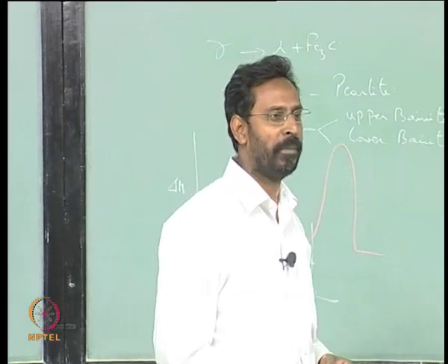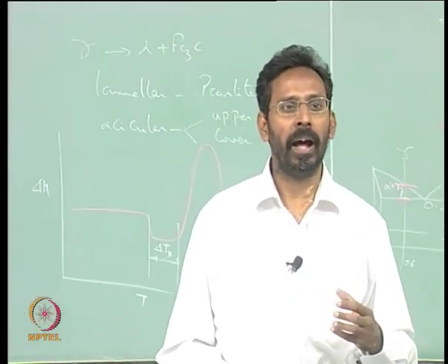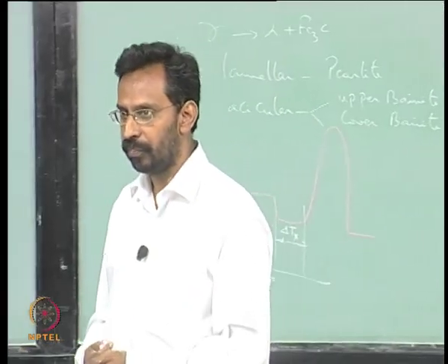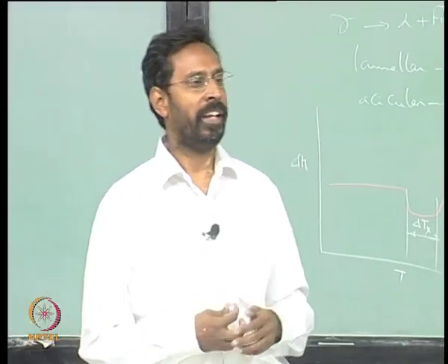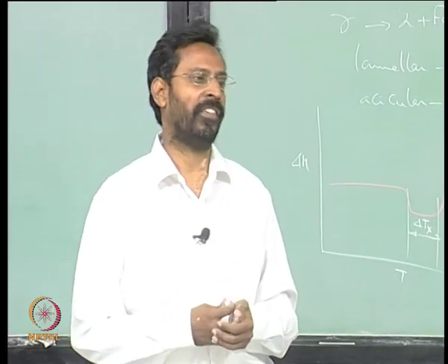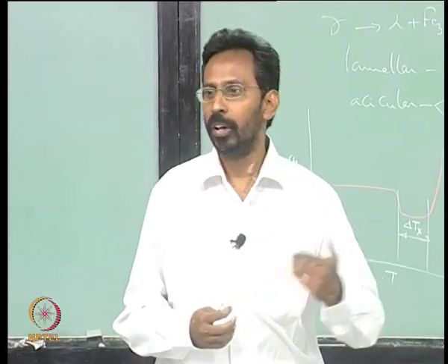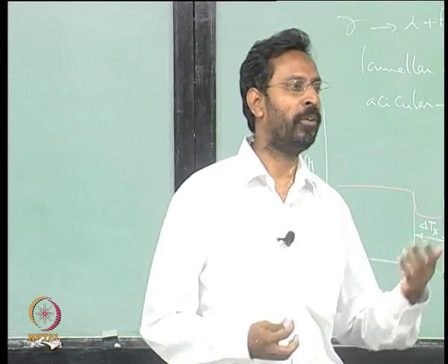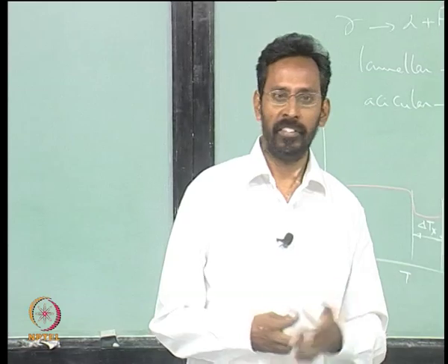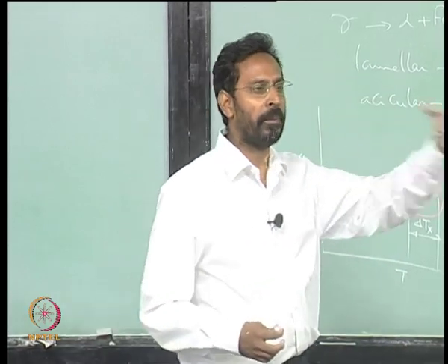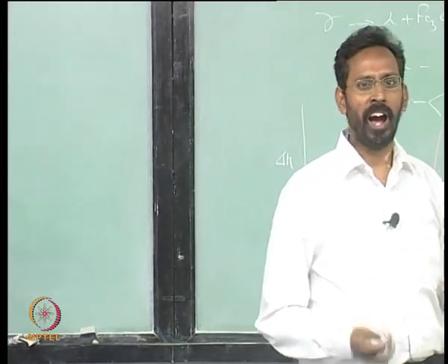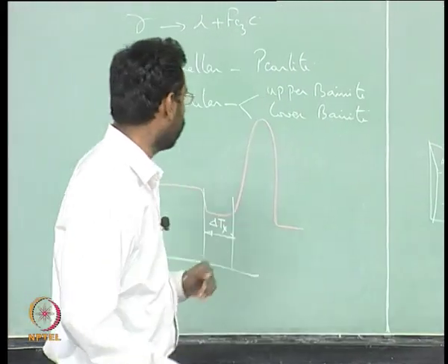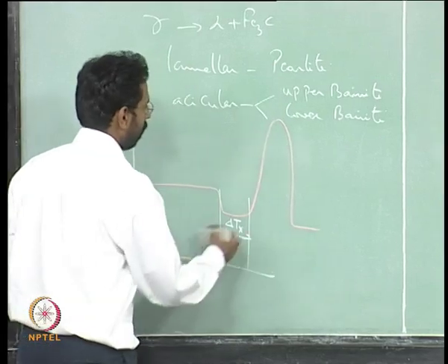Shot peening, there are many things where people try to induce compressive stresses on the surface, okay. Hardening is one way, even inducing compressive stresses on the surface, so that there is an increase in fatigue life, for example. Everybody knows fatigue life increases when you do shot peening, so it is simply that. So you either make the crack initiation more difficult or crack propagation more difficult, one of the two. If you can do that, you can make a material tougher anyway.